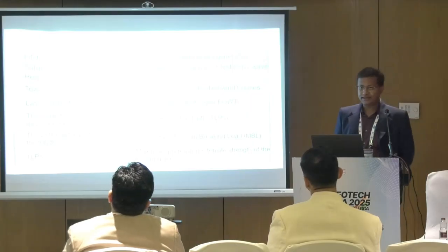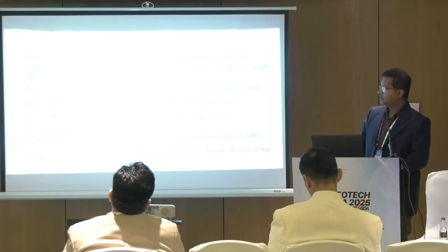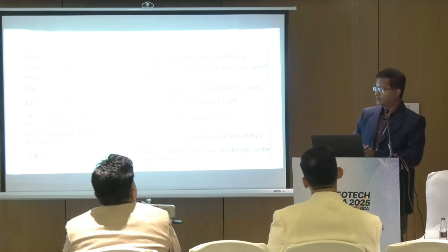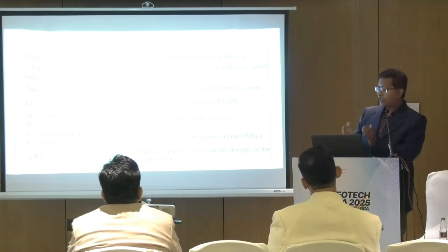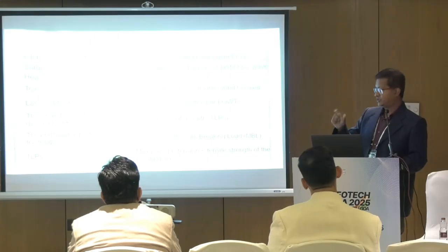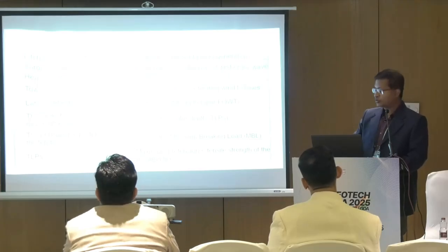So if you look at it, the design criteria are totally different. It is not a regular structure. If you look at the different possible modes of vibration, when the structure is deployed, it's a floating system. Therefore, it can rotate, it can have vertical vibration, it can have lateral vibration. So we have different types of modes of vibration: pitch and roll are the rotational modes of vibration, heave is the vertical vibration, and sway and surge are the lateral modes of vibration.